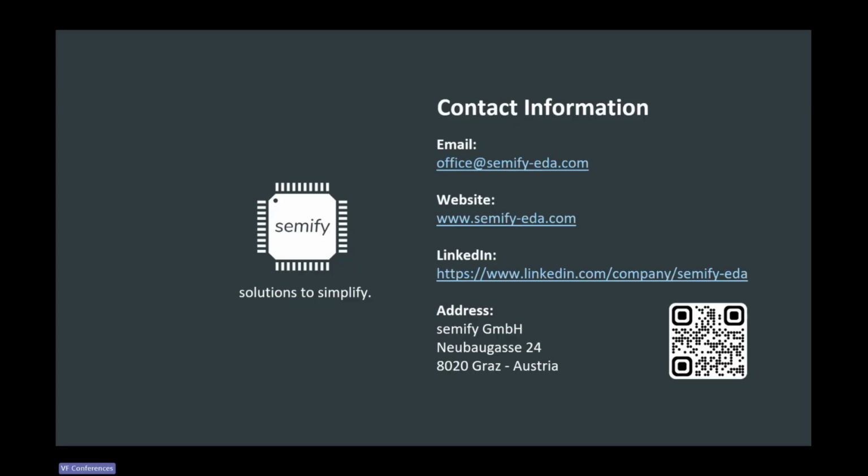Do you have some data on what's the simulation impact with the model that you have? Yeah, that's a very good question. Actually, something I didn't get into. I mentioned this model is pretty good for large designs. Part of the reason is that the overhead of using this model compared to just a standard 2-flop synchronizer is actually quite low. In the repository, I did some benchmarking, and I found that using the model with all the extra features, including a glitch monitor which does some background checks, was less than an 8% overhead compared to a regular 2-flop synchronizer.